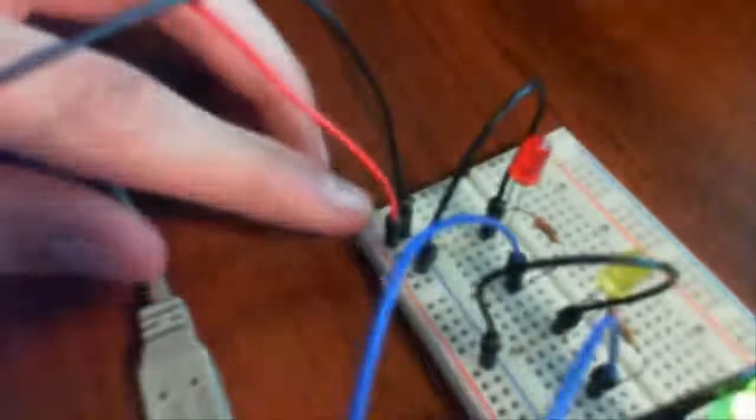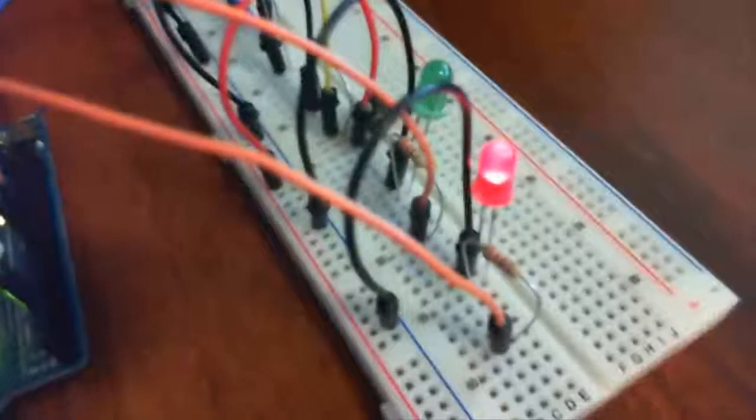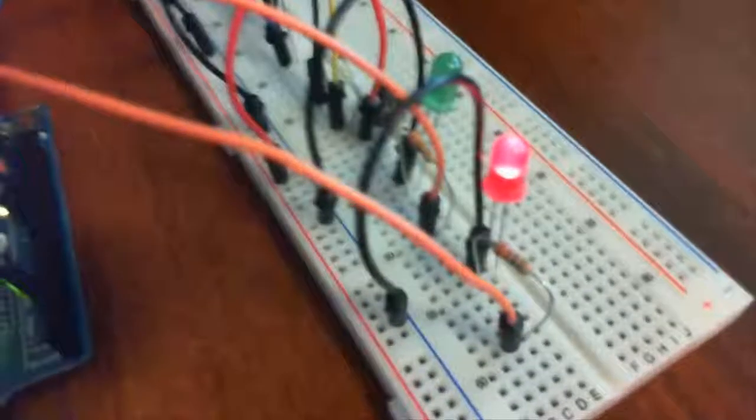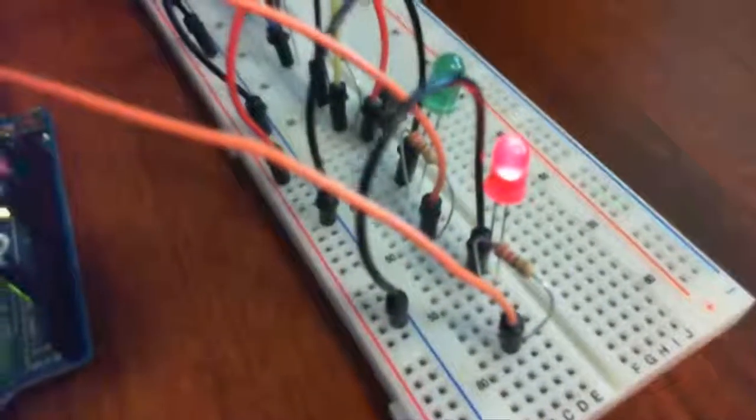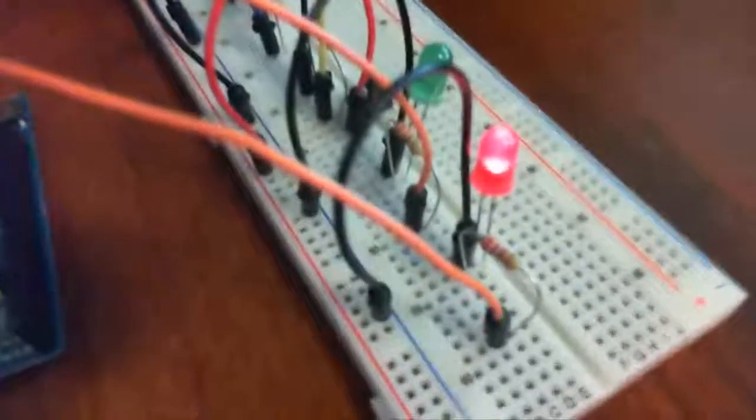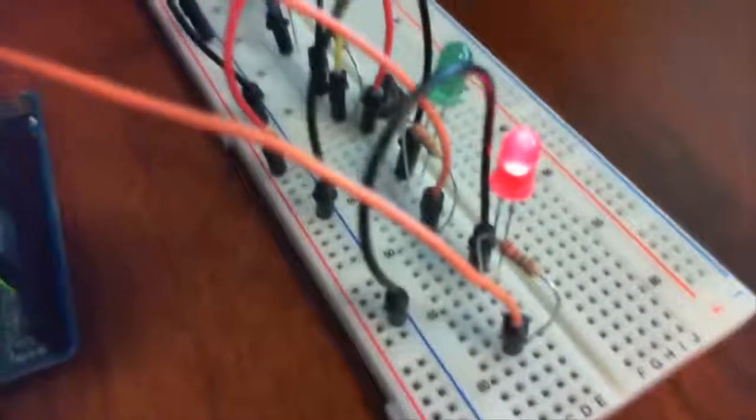right there, you have the black wire for the ground, this one right here, and the red wire for the 5 volts. Going in over here, you have your positive and your negative, of course, and then you can see, I'll show a better lineup. Each one of those resistors plugs into the high part, or the rounded edge of the LED, and that goes to the outputs, and then the other side of the LED is going to ground.